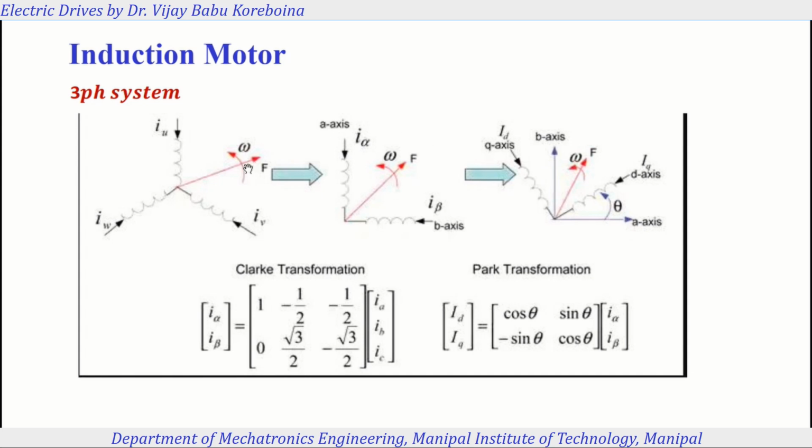Now, since this resultant vector itself is rotating, the quadrature axis of the resultant vector will also be rotating. Hence, this entire 90-degree axis system will be rotating at speed. So all quantities are in a rotating structure.